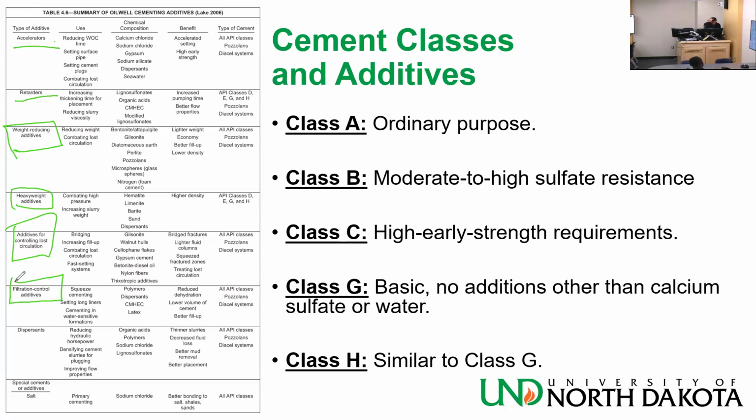Filtration control additives for squeeze cementing, for long liners, and so on. Polymers, dispersants, latex, CMHEC. Now on dispersants, again, it basically thins out the cement.